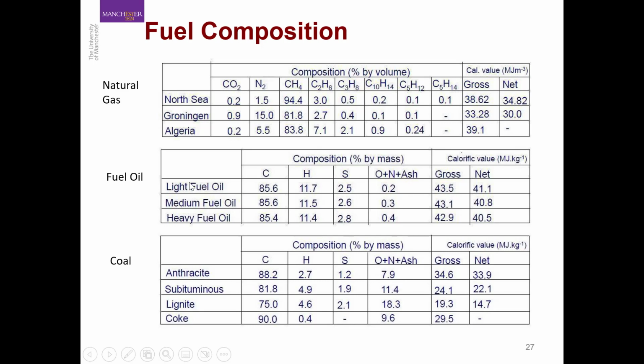If you burn liquid fuel, you are going to produce a lot of SOx, and that SOx can react with other components or with the metal itself and cause corrosion. It can also react with hydrogen present in the system and create hydrogen sulfide, which is again a very toxic gas and causes acidic corrosion as well. If you talk about coal, you have a very similar situation. You have quite a lot of sulfur present as well, so you're going to have the same problem of SOx generation as for the liquid fuels.